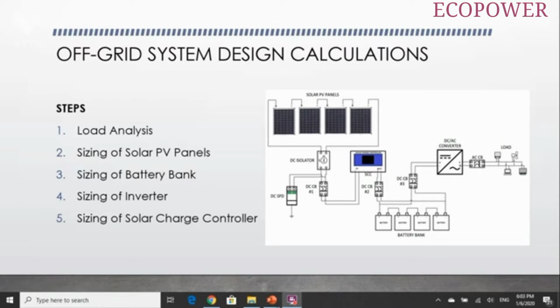Step number 2 would be the sizing of the solar PV panels. Step number 3 would be the sizing of the battery bank. Step 4, we'll size our off-grid inverter, and step 5 we will size our solar charge controller.